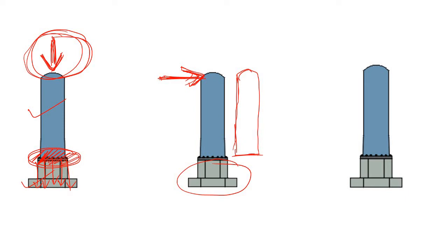So what we have to do in that case is simply fix this junction by using some anchor bolts. Now the sliding of this vertical column due to this lateral load is restricted. Once you have restricted this sliding, what will happen? You have some lateral load, and you have fixed this base by using anchorage. So due to this lateral load and the fixing of this base, there will be some bending moment acting like this.